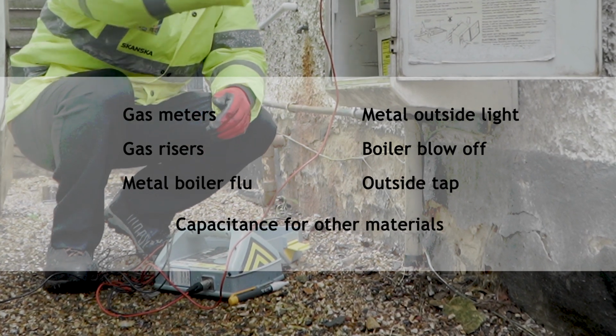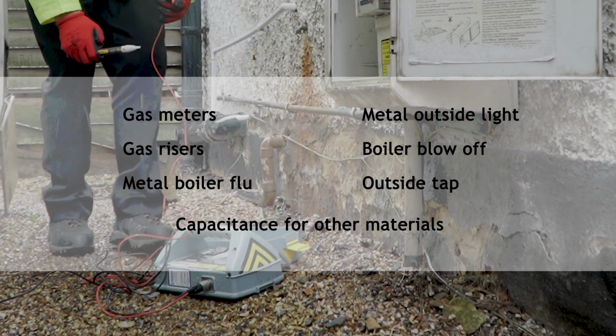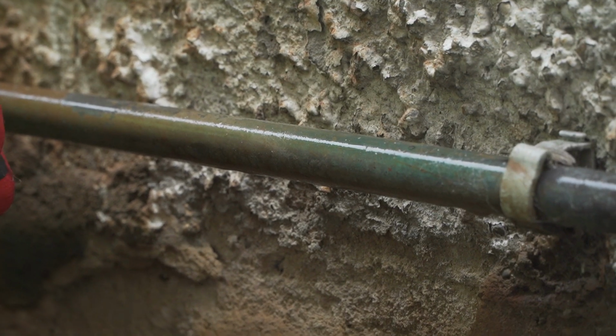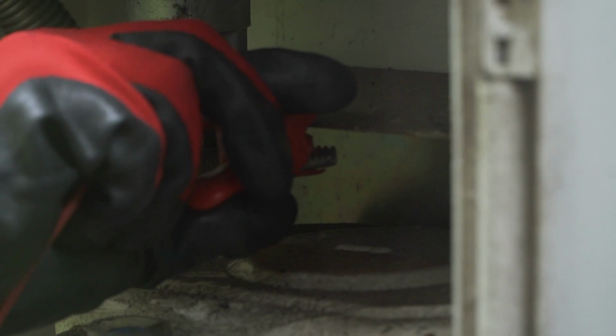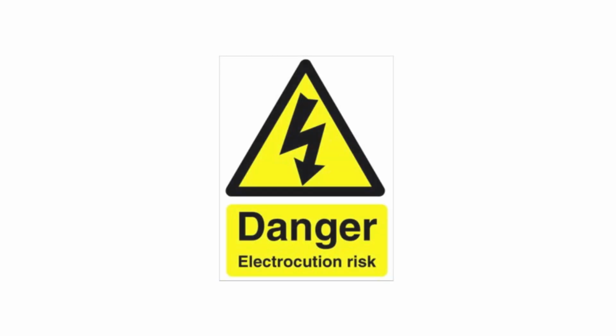Capacitance methods can also be used here, for example, by wrapping the lead around a plastic light fitting. All of these will usually connect to the LV service in the property and allow a Genny signal to be sent down the LV service and also along the LV main. Multiple connections to multiple properties may be needed to locate the whole LV network. It is essential that the LV network is located using the Genny before any excavation work commences.